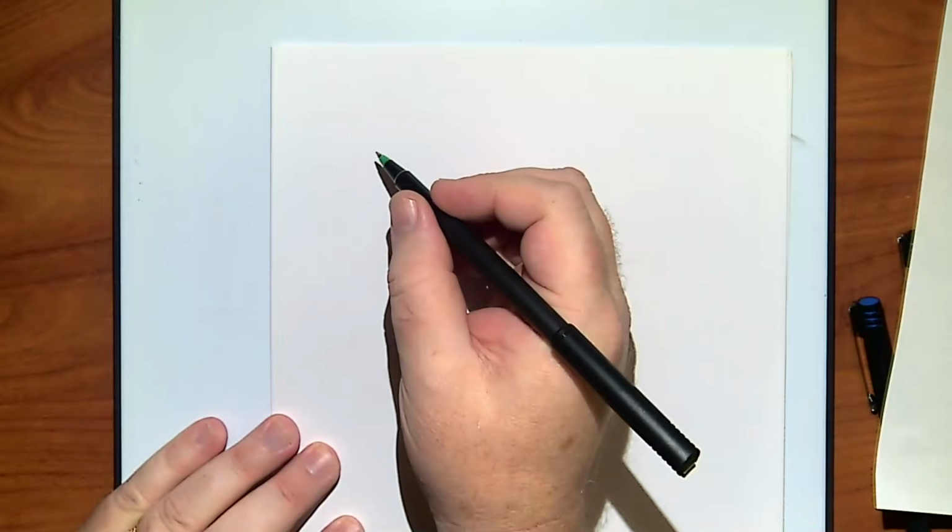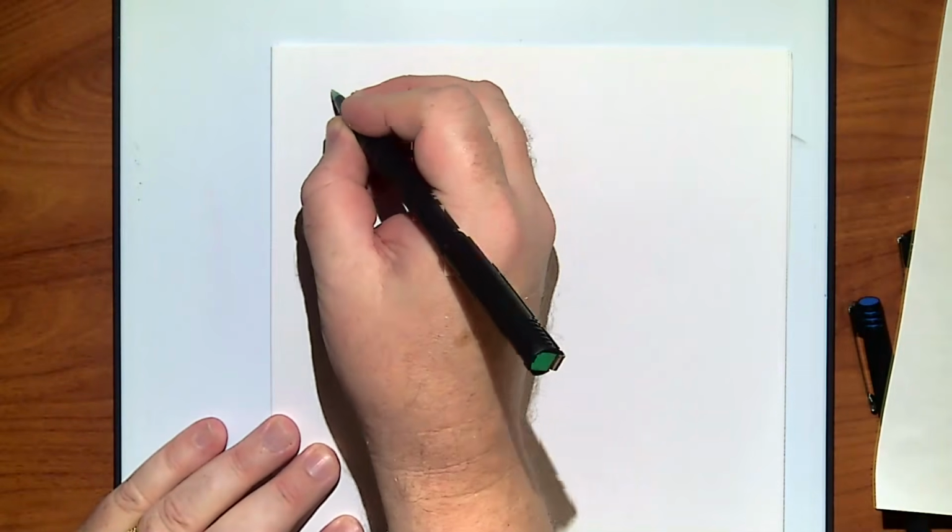What else? Hopefully I can go the other way. This is just the way I'm used to writing. Let's consider the first bit for a sec, right? So I'm trying to calculate some bit 0. So we're going to assume the gates, right? I've got x0 plus y0 plus potentially c0 carry coming into it. Adding those three together gives me some sum 0, and maybe some carry to 1. That makes sense? All right.